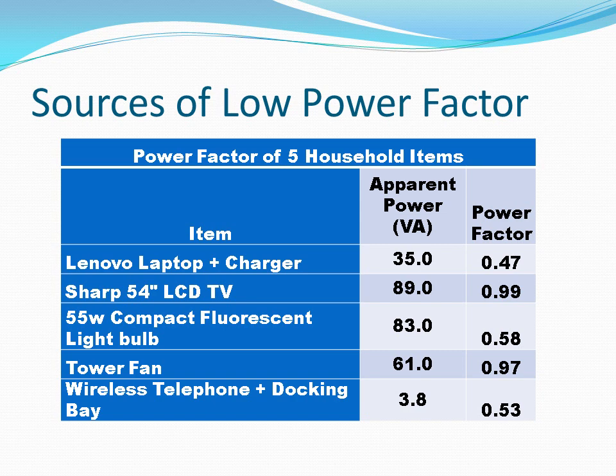So why is this the case? Some products have to meet worldwide standards for PFC. The most stringent standards are in Europe. We will discuss these standards towards the end of the video. For now we will suffice with the explanation that the TV and tower fan are made for a worldwide market, where the other products are intended for a North American market, and do not have to adhere to the same standards.